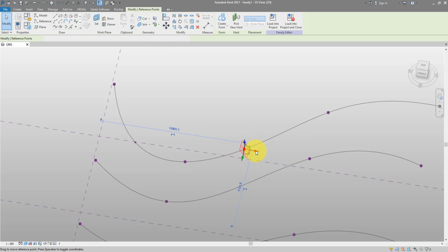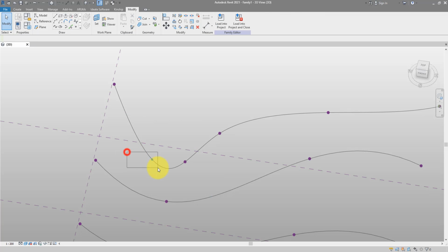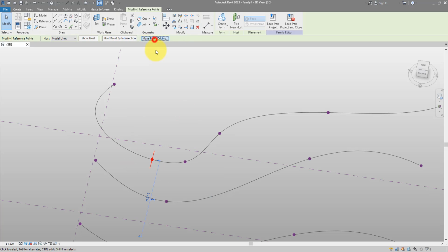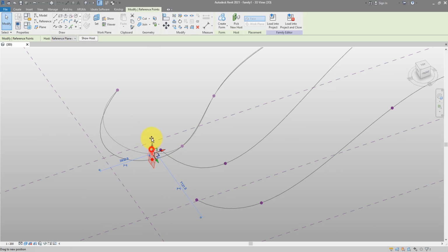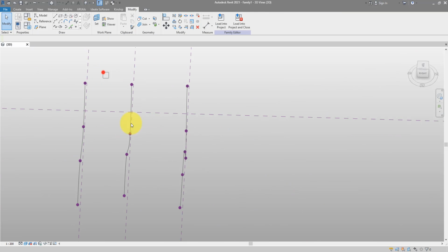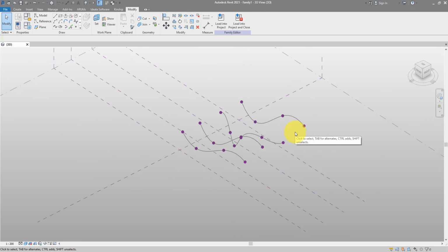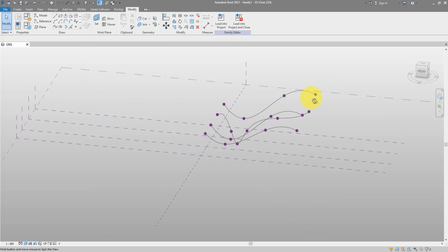If I now select this new point again, I have my arrows. Now I can use it to my advantage like this. Let's do the same for this other one. Select, make point driving, and then select it again. Now you have the arrows. Here we go. I can now select this and make another profile using the same technique. You can go for as many profiles as you like to create a complex surface. For now, for demonstration, I will finish with those 4.